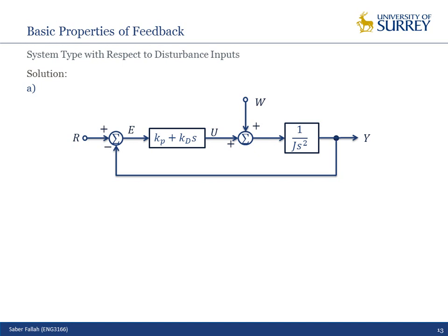That's great. Who agrees with 2? Okay. Why 2? 1 over s squared. Exactly. 1 over s squared because I have 2 poles at origin. What does it mean if I have the type 2 system?